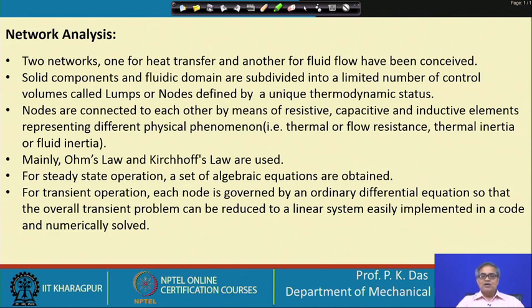In the wick there will be some sort of porous, again most probably metallic structure which is saturated with liquid. So, this liquid saturated porous media and the solid wall of the container, they contain the solid network, and obviously energy transfer takes place through this network.